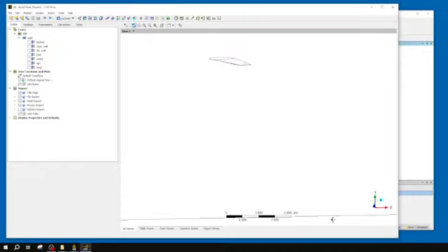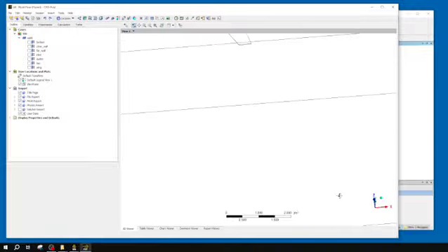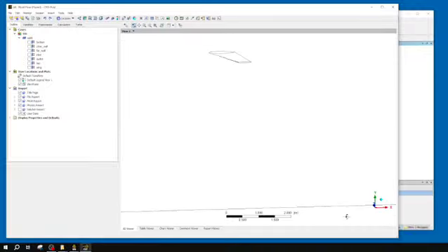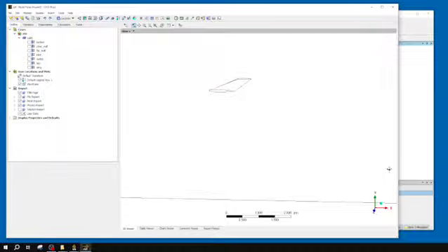That'll force it to stay in rotation plane. So even if I move left or right, it doesn't rotate, it only rotates up and down. And I can also do that in our other axes. So that's for your Y. Again, that's just going to the edge of the screen to do that.